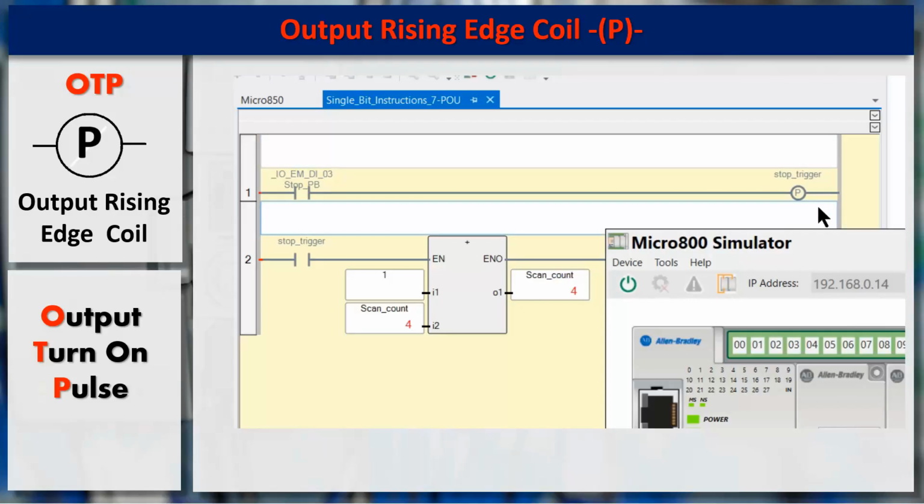It's the replacement if you can't look at an input or you're working with a particular output. For example, you want to see that your counter's working properly. You could parallel one of these with a push button that is being used to count, and the two counts should always agree, and if they don't, then you might have a loose wire, or maybe you're hitting the switch and it's getting a double pulse, etc.